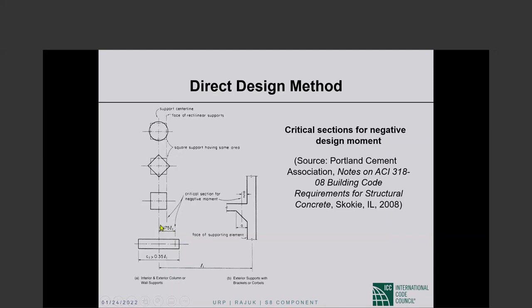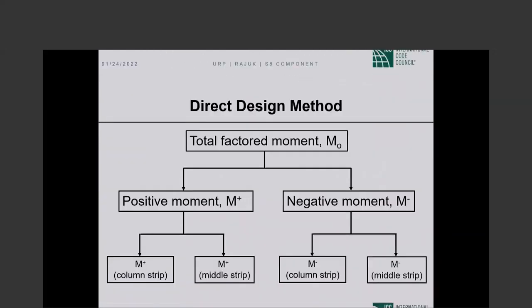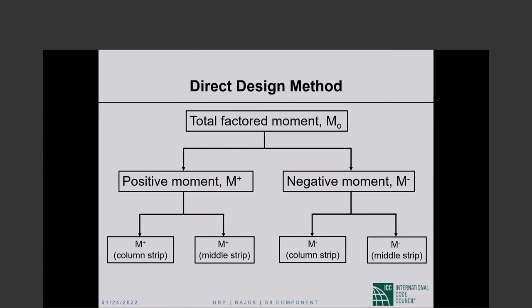17.5% of L sub 1 from the support center line, so that the span itself will be 65% of the clear span. Okay, and when there is a haunch, you go from the total haunch, which has a length L. The face of support will be taken from A over 2. So this picture, I think, tells you the whole story. I don't know that you will have to deal with any other situation.